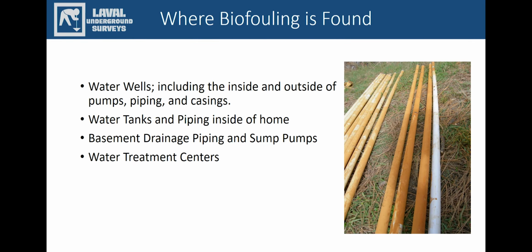Biofouling can really be found anywhere that there's a water source and soluble iron. Any water well can have this issue, and it includes all of the equipment associated with it, pumps, pipes, and casings, and as we talked about further, out into the screens. This bacteria does not keep to just one place. Piping to a house and the water equipment associated with it are also at risk for fouling. This is one of the main reasons it's important to keep up on the maintenance of the well itself, to prevent the biofouling from happening further on into the house.